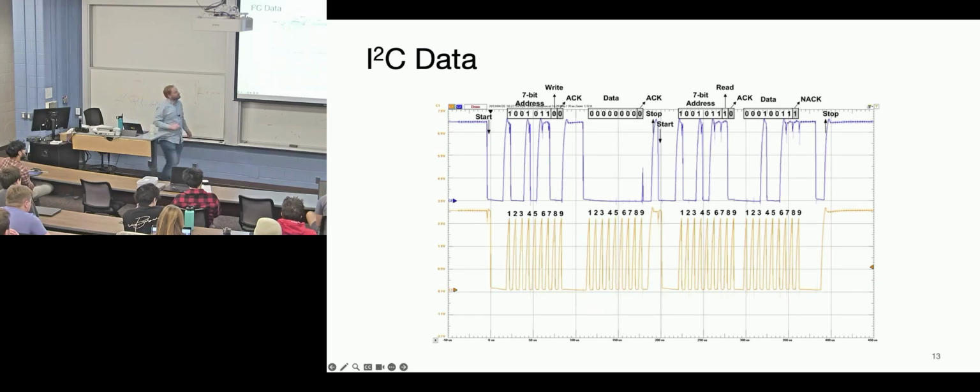And so this is an example of a data frame here. This is multiple reads. So here's a write. To this address, this data was written. To this address, data was read back. You can see the capacitance on the line here. We have this RC charge up. It's taking extra time for it to go up because those resistors aren't strong enough to pull it up very quickly.